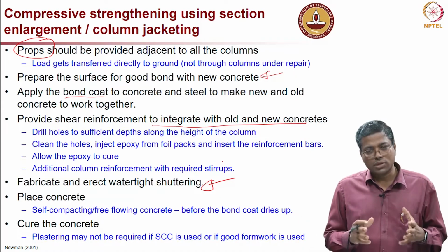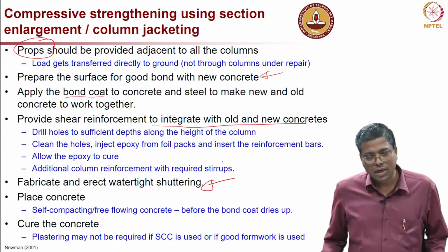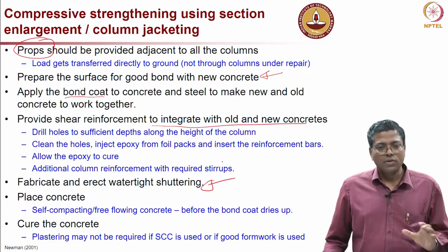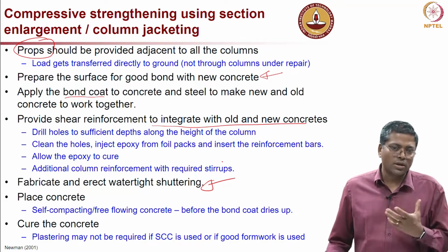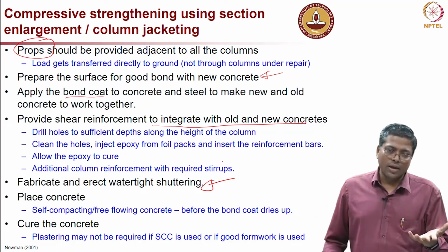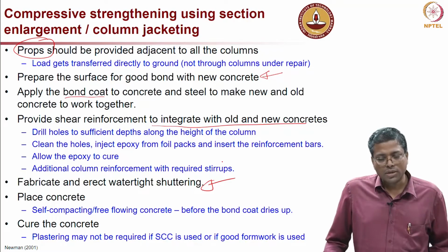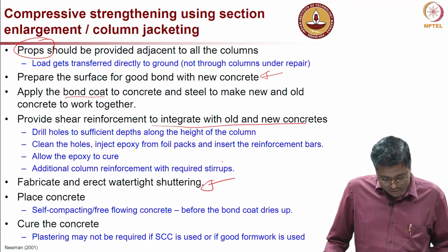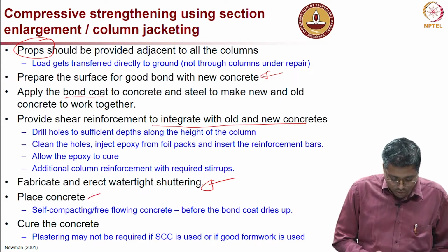If water comes out, it may be an indication of segregation, which will eventually lead to the formation of honeycomb, because if all the water goes out, you can have regions where cementitious materials are less. That is one thing. Then place the concrete.